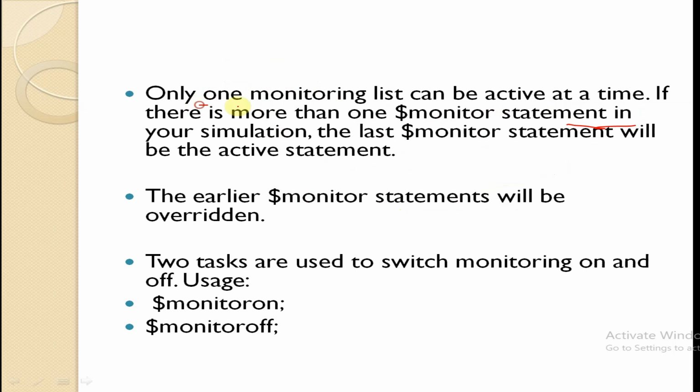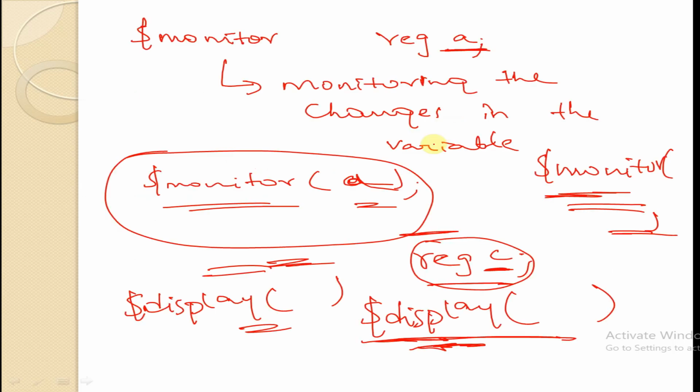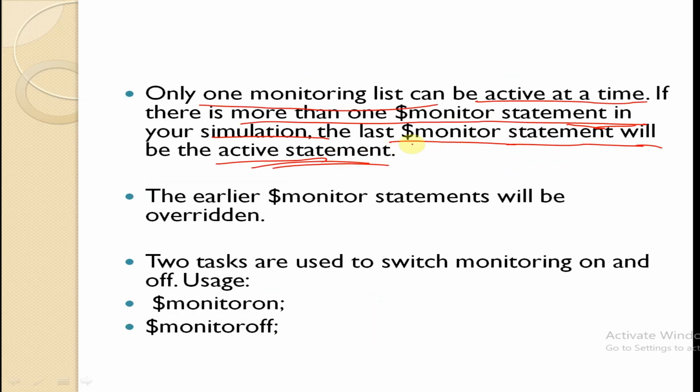Here we can see only one monitoring list can be active at a time. If there is more than one $monitor statement in your simulation, the last $monitor statement will be the active statement. So instead of using two $monitors, we will prefer only one, because the earlier $monitor statement will be overridden.